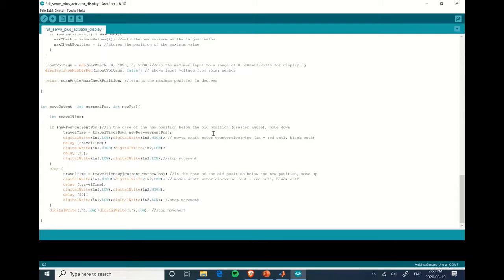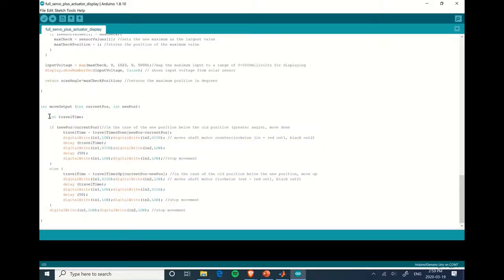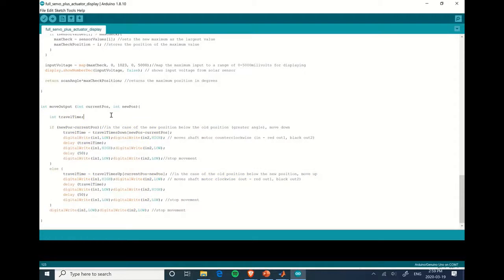And our control code was pretty basic in design. It was based on timing, so the amount of time that the H-bridge would allow for the motor to be on would determine the distance that it would travel and therefore the position it would achieve. So as you can imagine, there's a little bit of error associated with this, which you could see in our video, but as the arm travels back, the error seems to dampen out, so we didn't expect it to be too great of an issue.